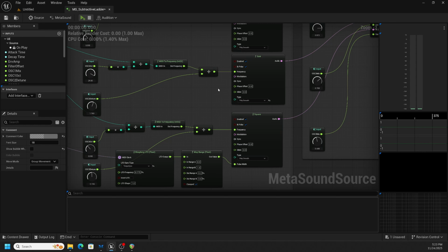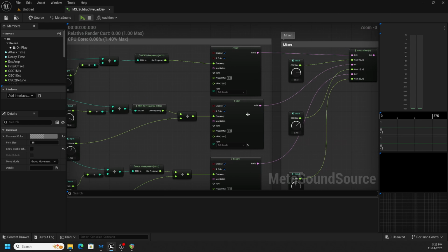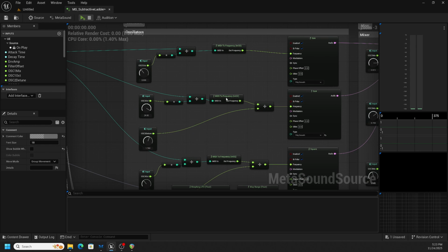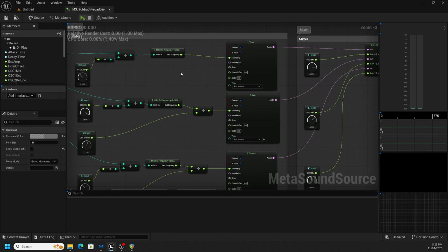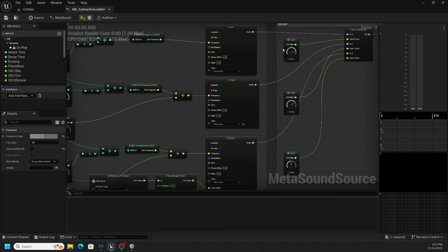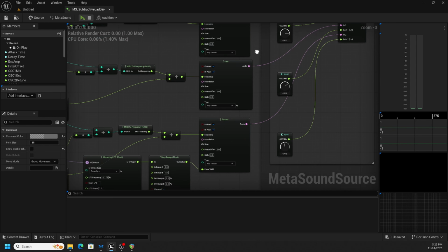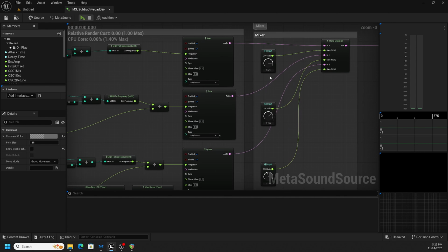to hardware specifications. So I picked 2 sawtooth and 1 square, and I think of this top oscillator as my primary oscillator, oscillator 1. And then we can decide how much of each of these are proportionately mixed together. So we have 3 different gain knobs for my 3 different oscillators, and those are controlling this mixer. So oscillator 1 feeds into the input here, oscillator 2, another sawtooth, feeds in this input, and so on with the square wave into here.